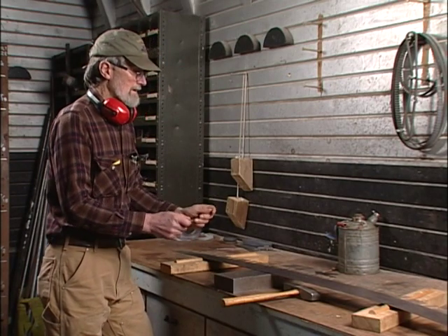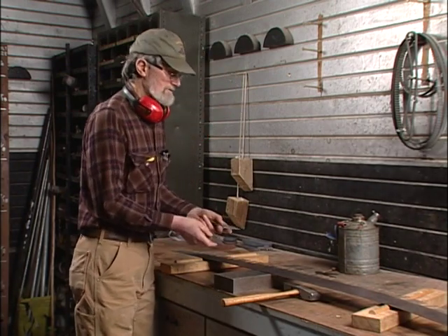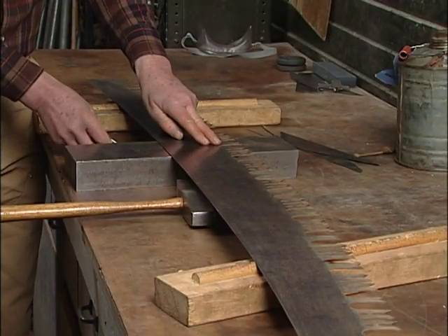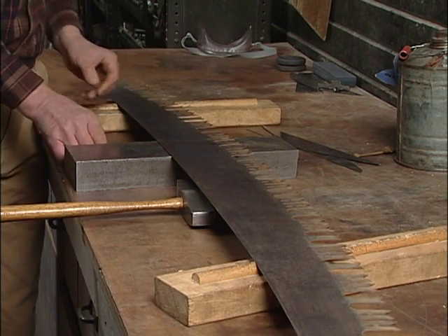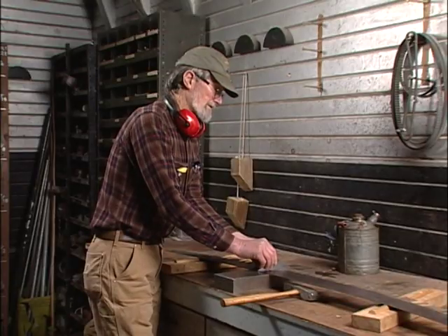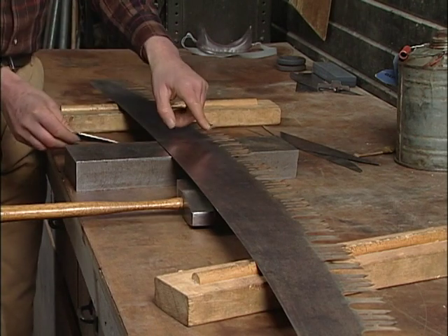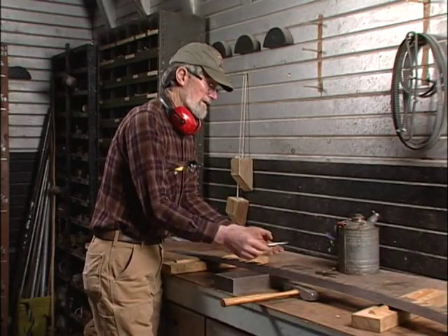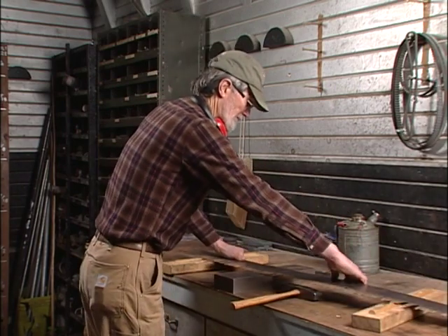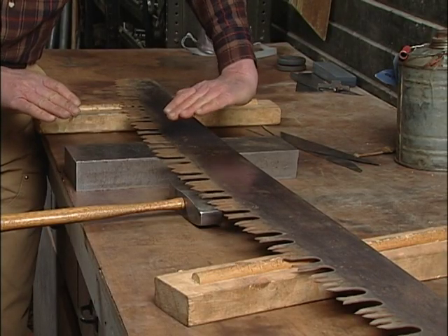When I was initially doing the testing of the saw with the short straight edges, if I were to have determined, for example, that this raker had a serious bend in it in this direction, so that as I run the straight edge across like this, I find that this raker is bent this way, and hitting the straight edge, then what I would do is turn the saw over so that the convex side of my bend is facing up.